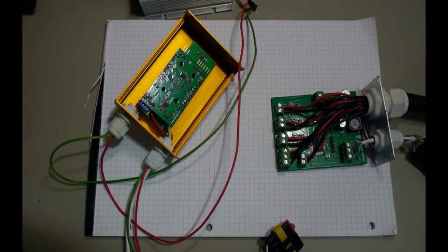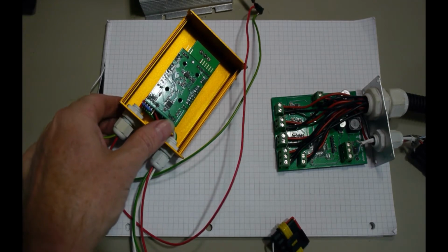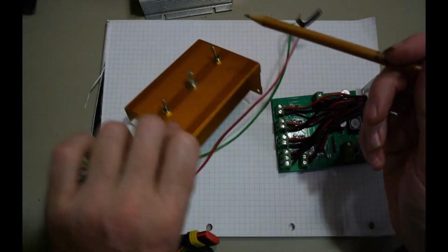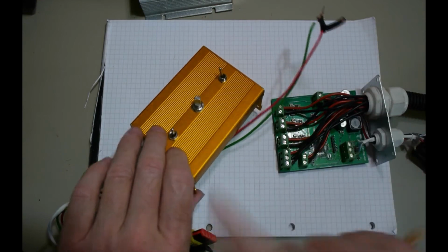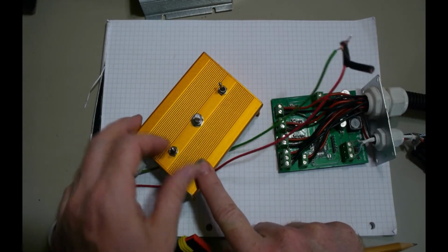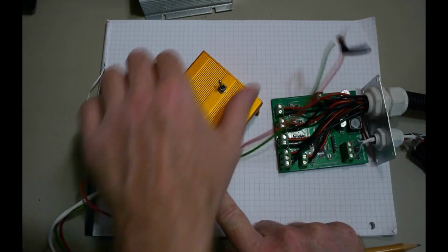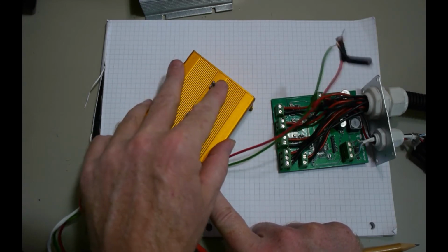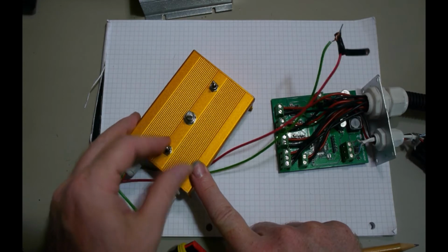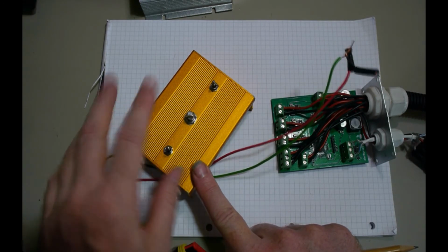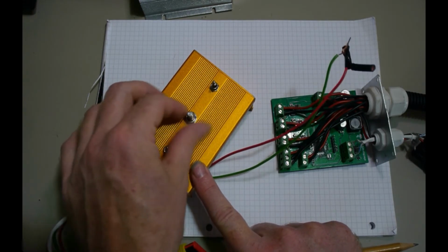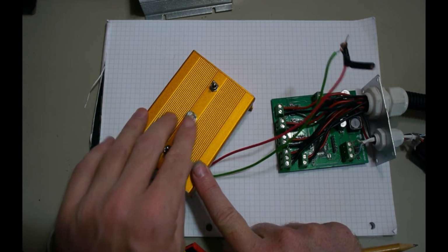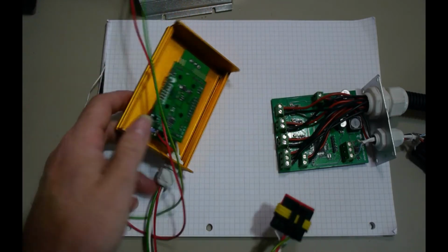Hello again, YouTube. I'm just going to finish up this mower project, the mower controller. This in the gold box is the human input device. It is basically one momentary switch, one toggle switch with 3 positions, momentary switches with 3 positions, and an endless encoder. Now there is a switch when you press it. I'm not using that at the minute.